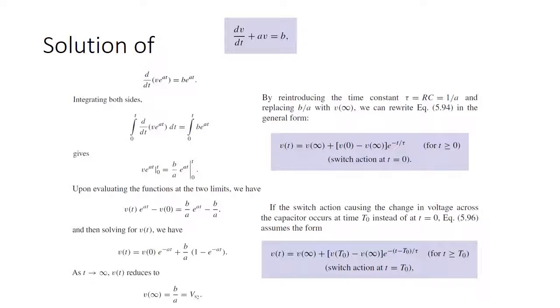That saturation point happens when the voltage at the top of the capacitor is the same as your source. Then your capacitor is going to act like an open circuit, and no current is going to flow through here. So logically, this makes a lot of sense if you think about what's happening, as well as solving the math.